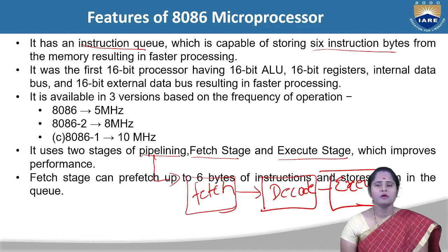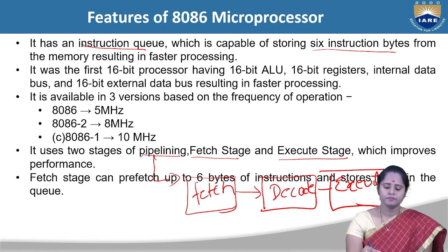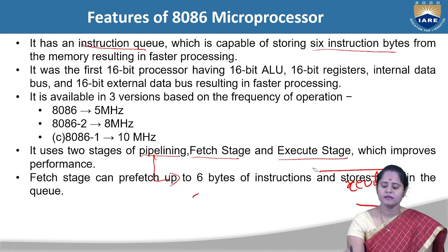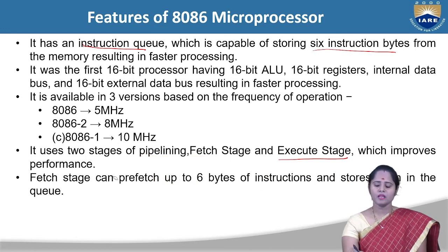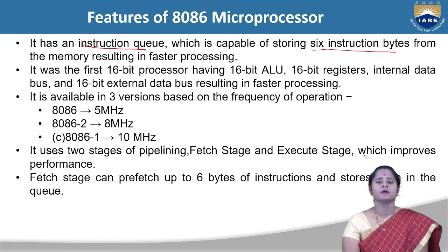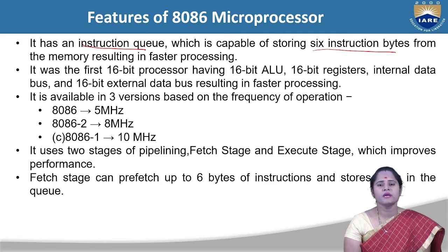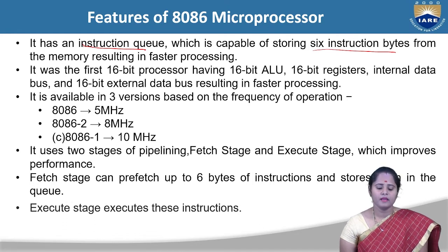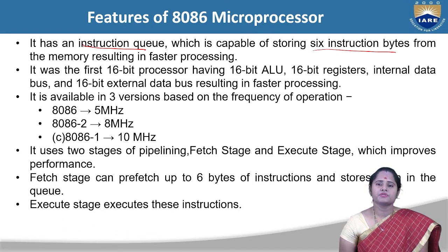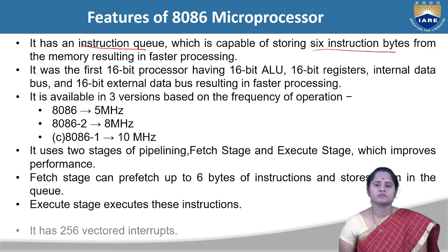So here, what is a fetch? As we said, in the execution unit we have an instruction queue which has 6 bytes. So from the 6-byte queue we fetch the instructions one after the other and execute them. And the execute stage executes those instructions.